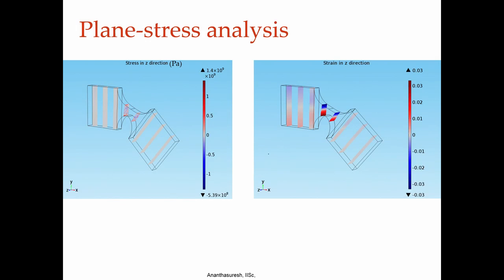So, here this is shown using what is called plane stress analysis. When you have a 3-dimensional structure such as the circular flexure, if you were to take the 3D model and do the deformation analysis, you would get the correct result if you were to use a fine enough mesh. That is something to remember in finite element analysis, that you have to use a mesh that is fine enough to give an accurate answer. If you use too few elements, you may not get the accurate answer. So, you have to mesh it in progressively finer fashion until the result does not change significantly.